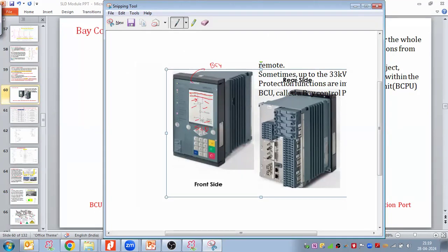We also have the equipment opening and closing switch here. By selecting the switchgear with the change options and using these press buttons, we can switch the equipment on or off remotely from the control building. We also have the LED indicators, which indicate the status of the equipment.